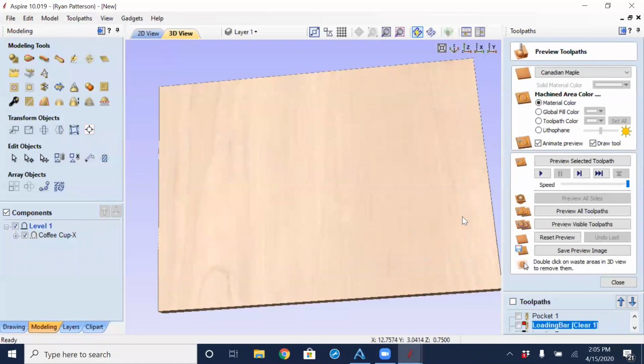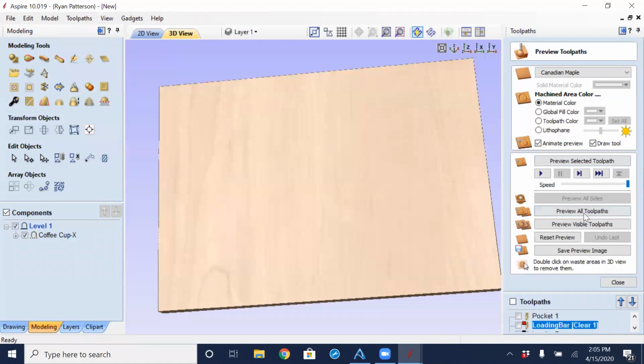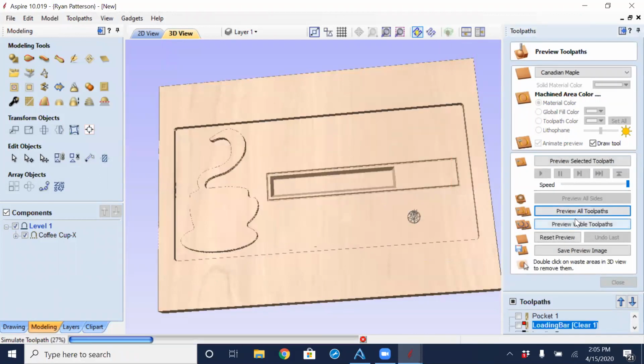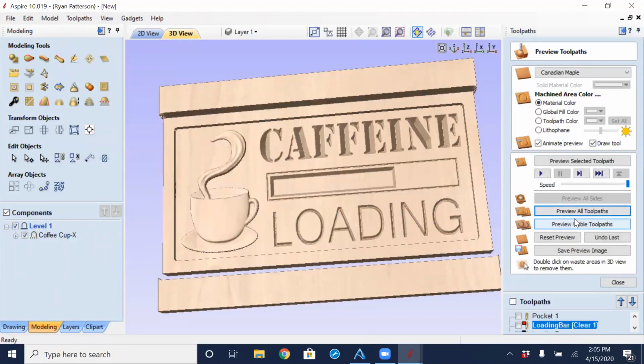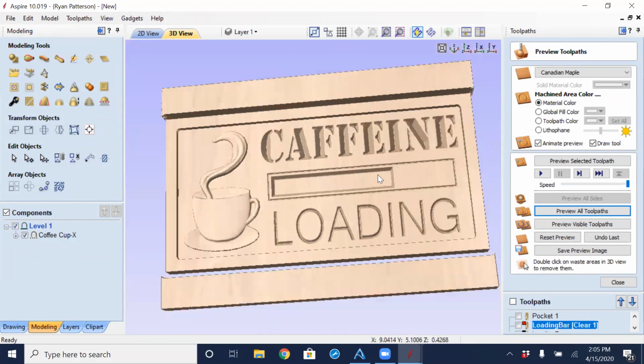This looks like setting that to the standard. And now, I'm sorry, preview all the toolpaths. We'll see that the overall preview went a lot faster. In this case, this side's job really didn't make that much of a difference. We're able to see a little bit of clarity difference here and maybe along this line there. But for the most part, in this project, having that set at the higher quality wasn't giving me a whole lot of added benefit.